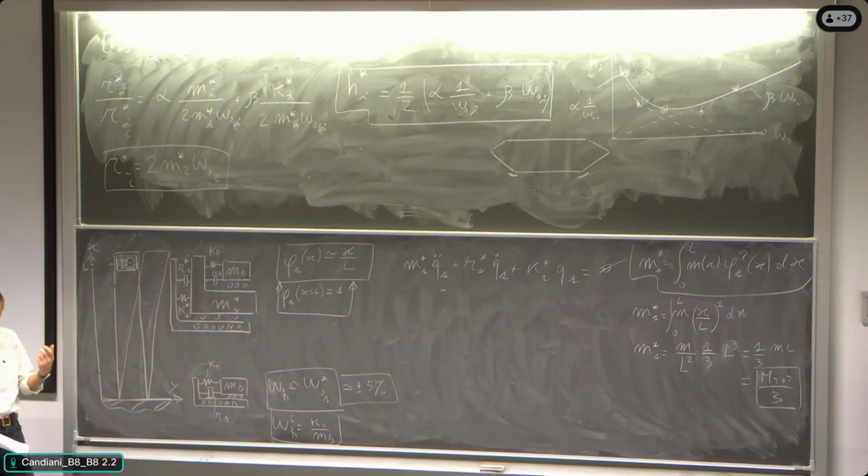The reason for making a meaningful normalization of the modes is to make a meaningful representation of the numbers, for example, of the modal mass. So it is very meaningful to say that the participating mass in this mode is not 1, it is 1/3. 1/3 of what? Of the total, under the hypothesis of uniform distributed mass. Very well.